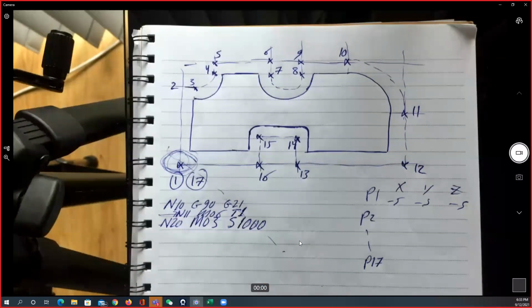When I said tool changer, I think that I explained that to you earlier, but I'm going to show you a video now. The tool changer is something like a disk, and this disk has multiple positions for the tools. So we can put a minimum of 4 tools on any turning machine, and we can take it up to 16 in some of the advanced machines.